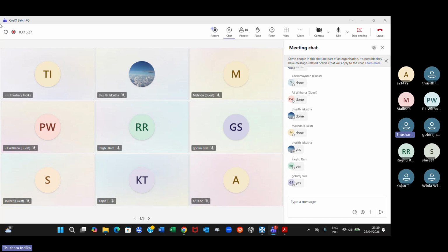How? Using the admin panel. In the admin, you have costing and rate library, and then you have something called constants also. If you want to use constants to calculate reinforcement quantities using ratios, then you can apply that. Plus, if you are measuring some structural elements, unit rates can be your constants to calculate the kg.